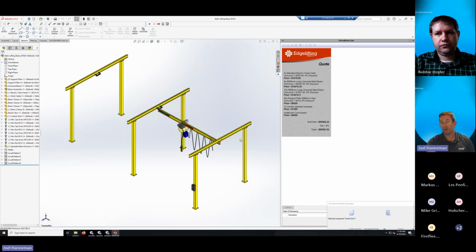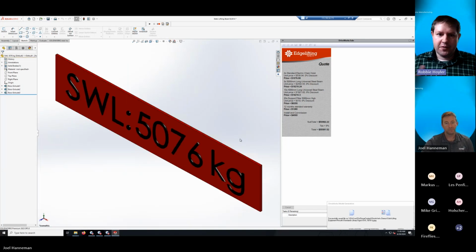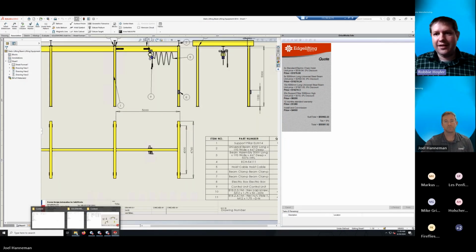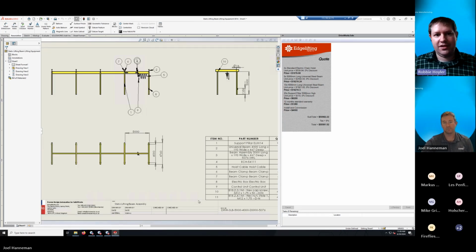Okay, as we can see, we're not using that kind of stand mount crane. DriveWorks knows, because of the length and the capacity and everything else I chose, we need a heavier duty option. So it's going to activate an entirely different assembly for us right away. So as long as we have a general scope of predictability for the model and we have our specifications, min and max, as long as this model can exist in reality between any of those specifications, it'll simply run that. And that keeps our drawings predictable, keeps our assemblies predictable.